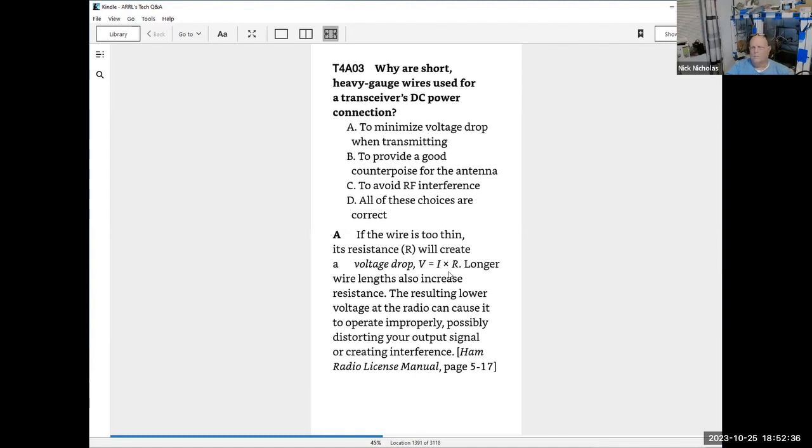And boy, that'd be great. Except you do have to worry about the voltage drop there. So I would tell you that you probably don't want to feed it with less than number 12 wire, which according to a household wiring chart is good for 20 amps. Well, that would be great if there weren't any voltage drop. And if you're only wiring a couple of inches, it probably would be great too, even at 12 or 13.8 volts.